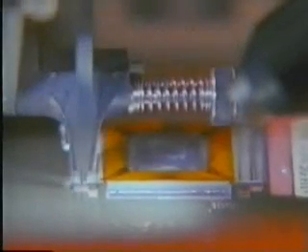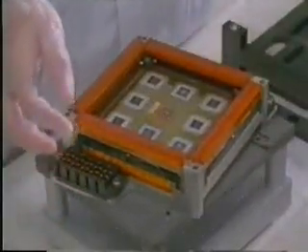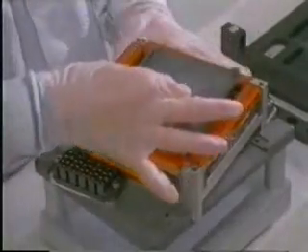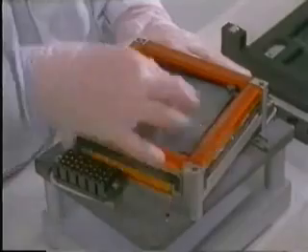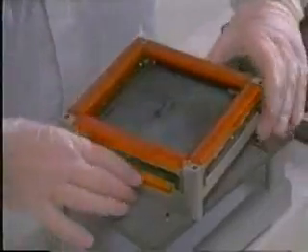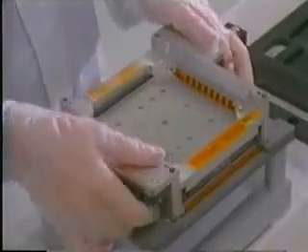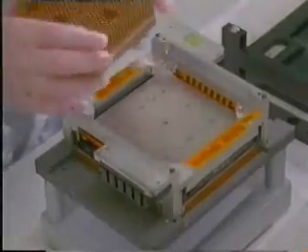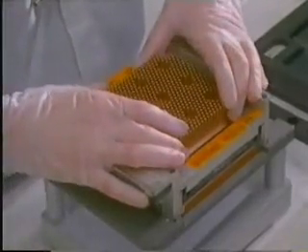Near the clock chip, a unique serial number is encrypted by interconnecting special pads. Using this number, a computer, if necessary, can review the manufacturing history of the MCU without having to remove it. After extensive testing, a lid is placed on the MCU to protect it from mechanical damage. Finally, a pin fin is attached to the back side of the signal carrier.